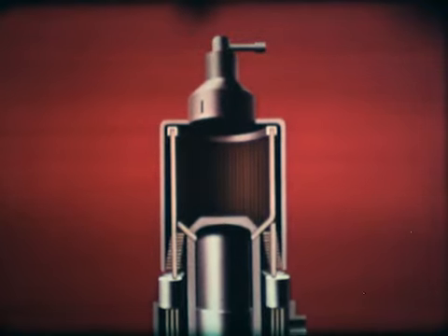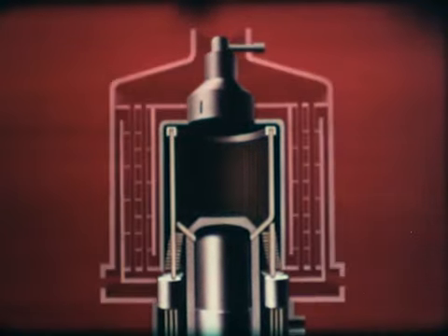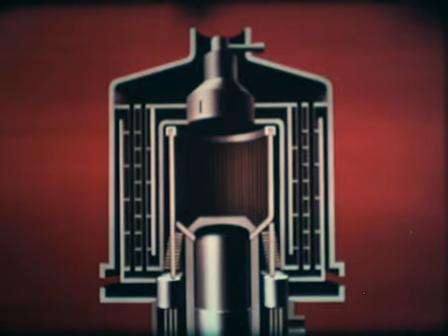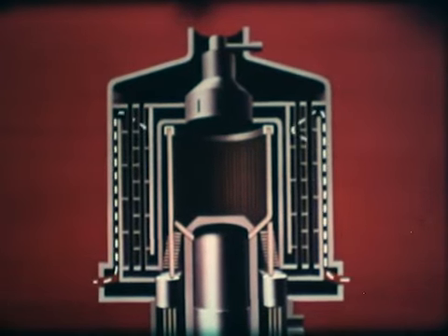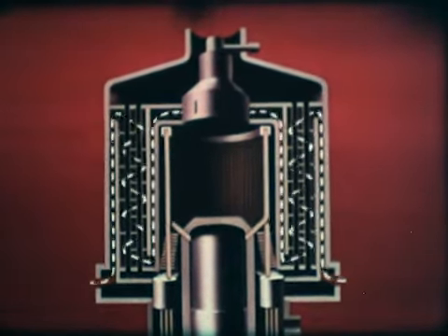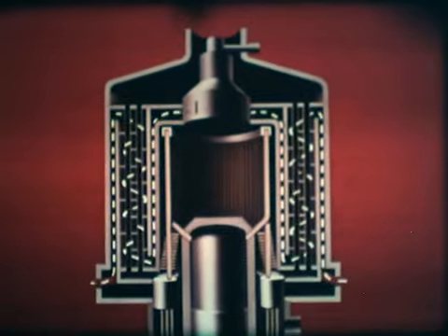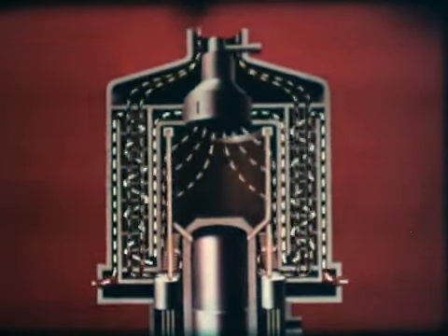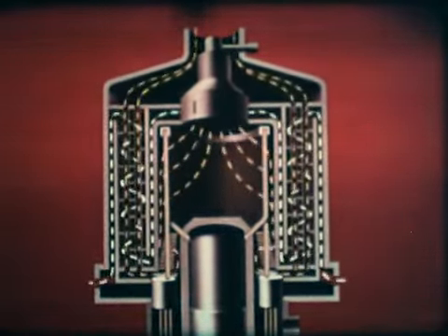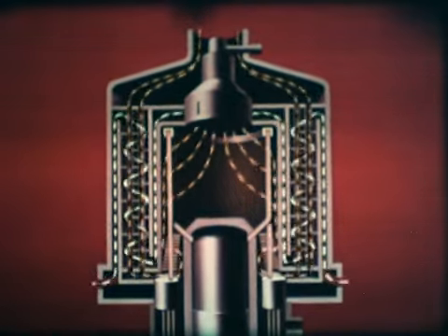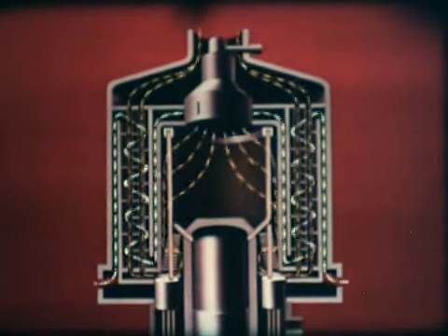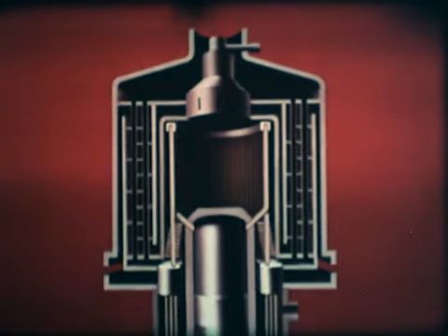The efficiency is increased by using a preheater. In this, the air is led to the burner against the flow of combustion gases, absorbing heat from them and thus reducing chimney losses. The heating system, being external, is very flexible indeed. It can be adapted to use nuclear, solar, or stored heat energy.